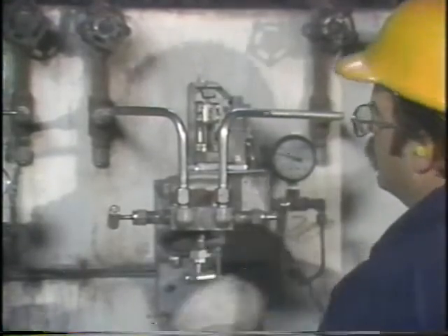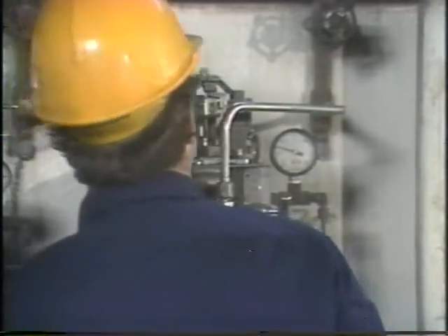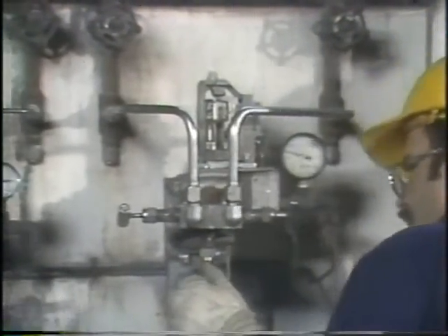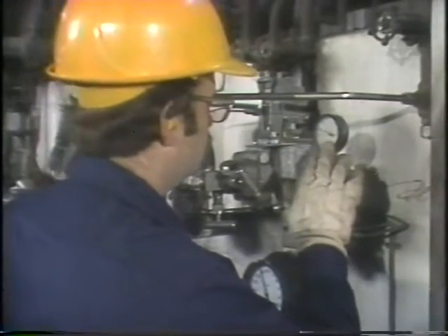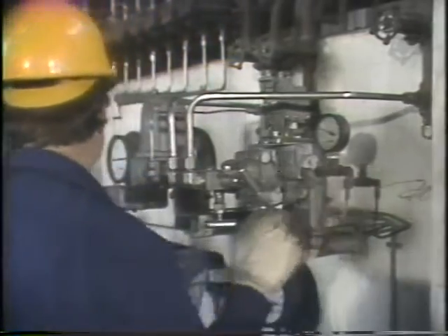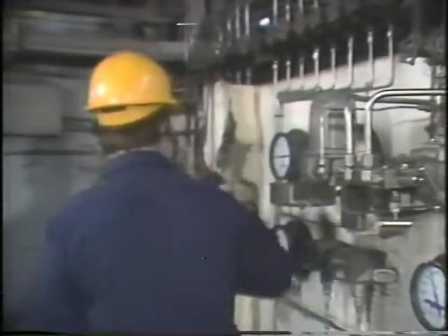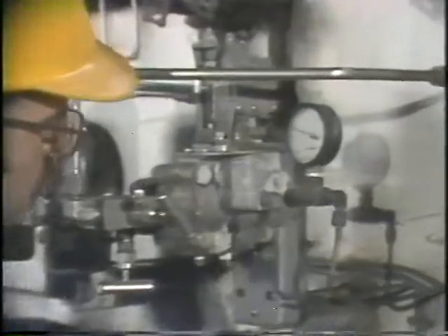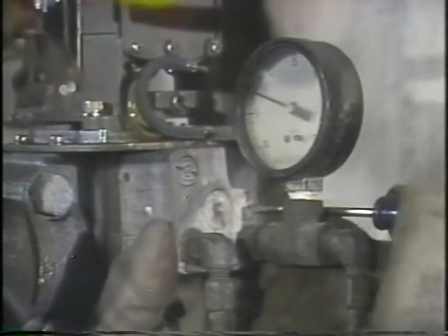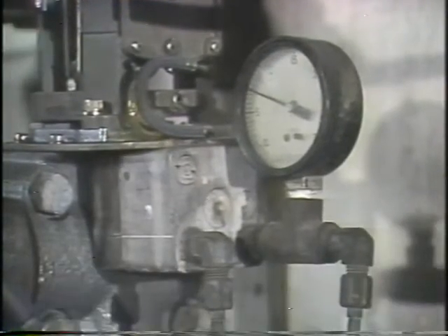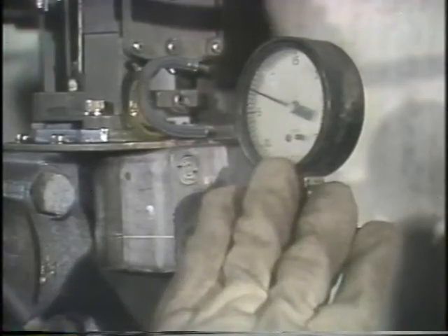Well, I don't see anything. There's no signs of leakages. Nothing appears to be damaged or broken. Don't see anything wrong here. Now, this transmitter does have a pneumatic relay. I'll punch out the orifices and see if that affects the signal. If they are plugged, cleaning them will cause the signal to increase. There, that takes care of that one. I'll get this one back here too. Let's see. No, the signal's not changing.